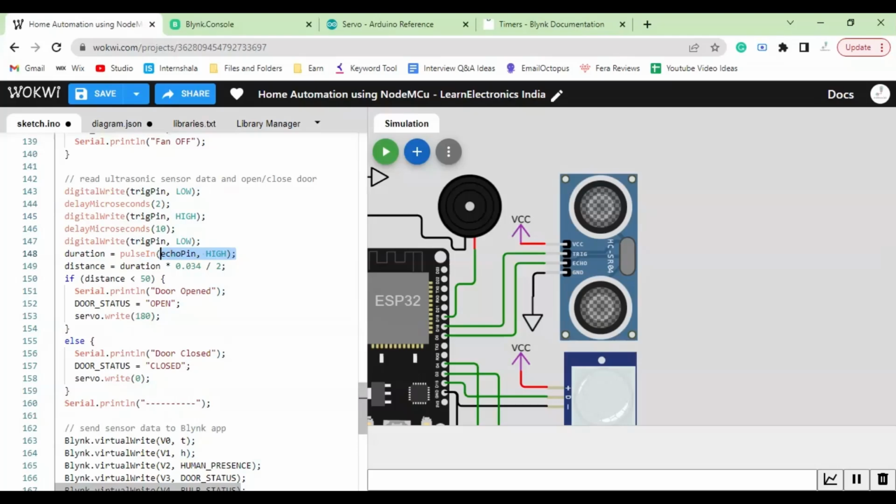So in this manner, we can understand there is a person or an object standing in front. Now, obviously, here we could have used the PIR sensor again, but why not use an ultrasonic sensor to understand? Obviously we can change this and convert it into a PIR sensor for human presence only. But for now, we just keep it as an ultrasonic sensor.